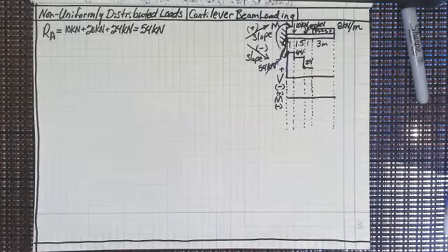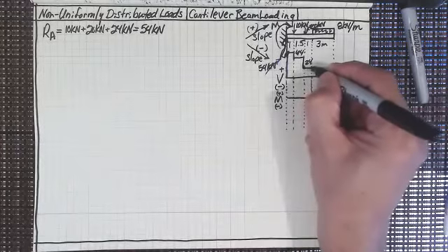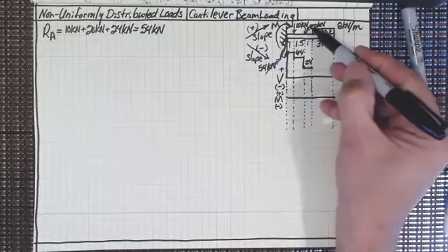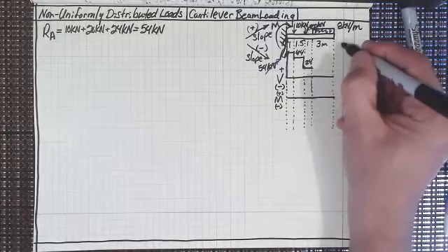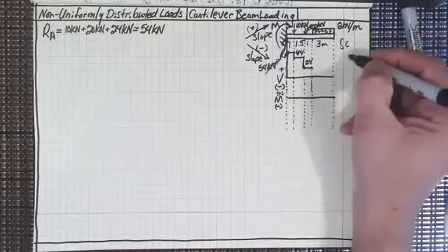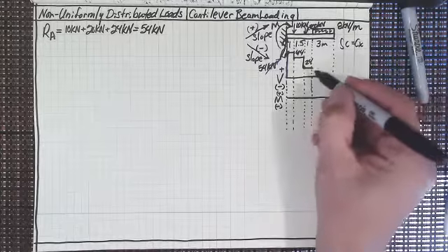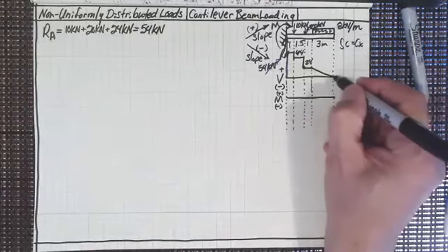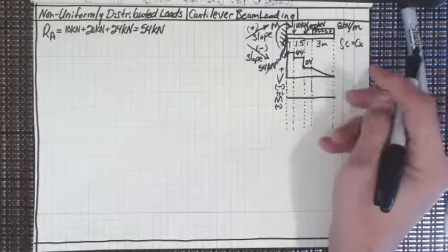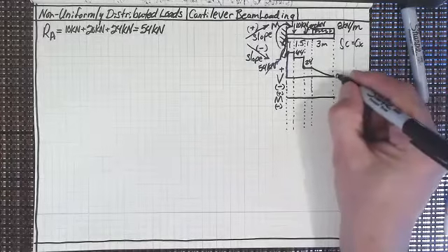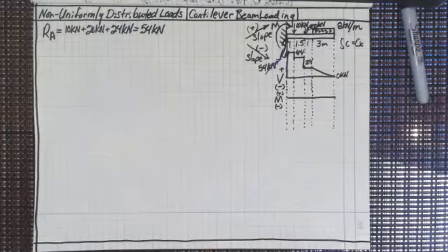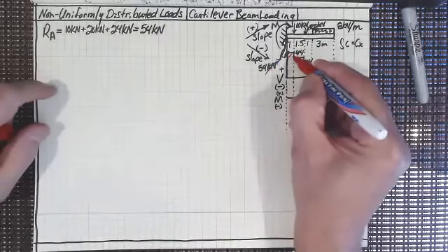And then at 24, because nothing has gone across there, what about here? Now we go down, because what is that? That's 24 down, and that's going to occur. Now this is a constant, so if I integrate the constant, it's going to give me a straight line, isn't it? Right? So 24, and then it goes down to eventually at the end 0 kilonewtons, as it should. So my shear force diagram is this.